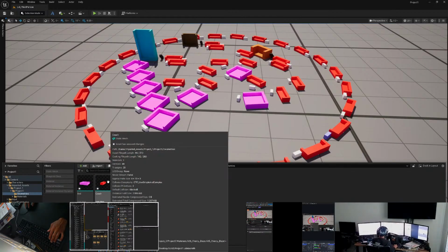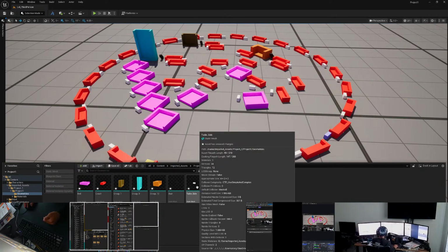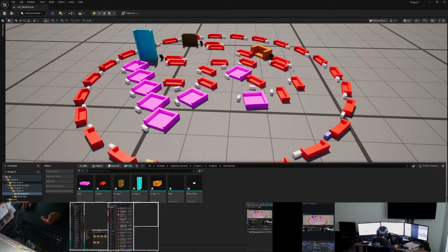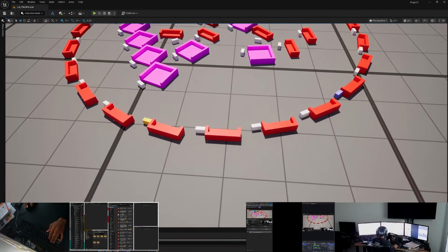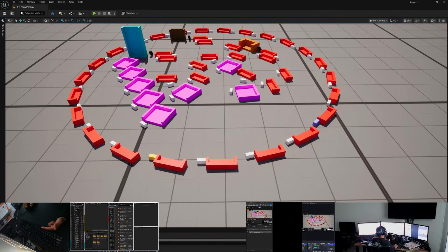Now, all of these couches are populated as instances across the scene. So, alongside the 7 materials, which I have as base materials for each one of these meshes, there are 2 additional materials that are unique for 2 of my little side tables. So 7 meshes, 7 materials plus 2 additional materials. That's 16. Technically, that's 16 draw calls on the GPU, right?